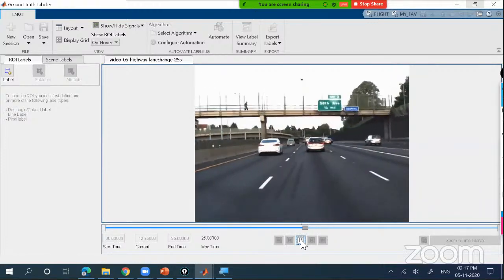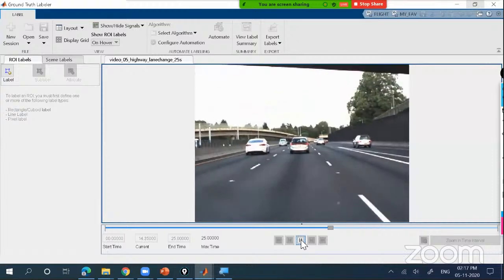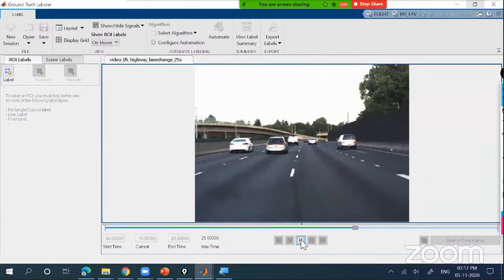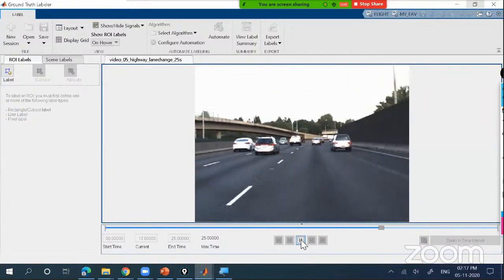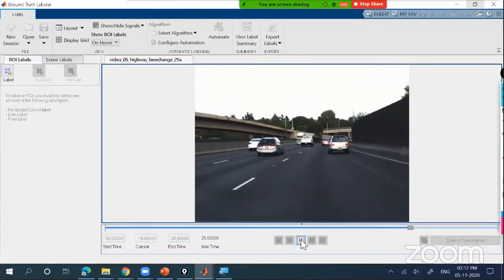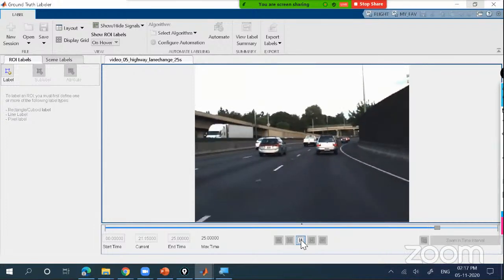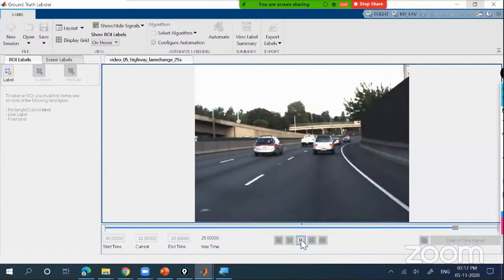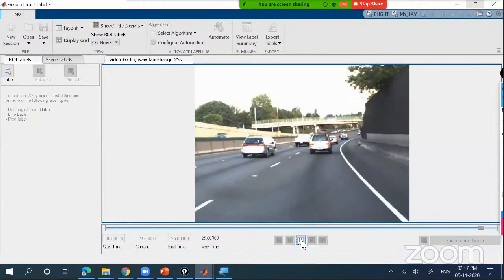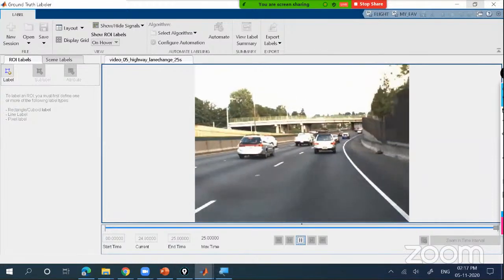Now you have to write an algorithm where the vehicles moving in front of you are identified, like the video we just saw in the morning where the Volvo vehicle was able to identify the vehicles in a real-time scenario. So let's go ahead and build this model. This is the entire video which is there inside MATLAB, which you have just invoked inside the Ground Truth Labeler app.